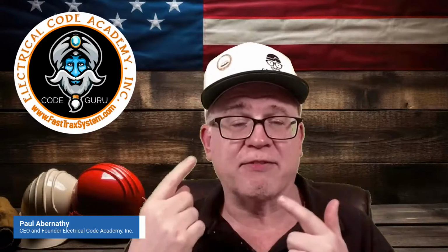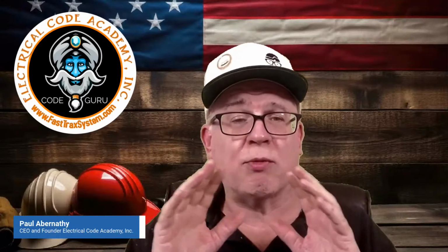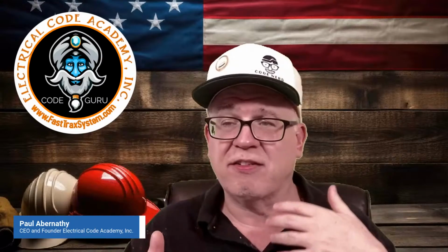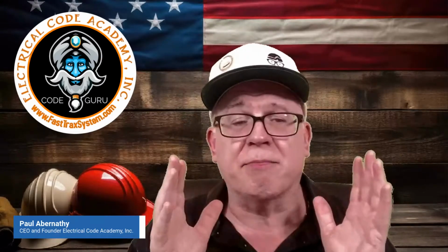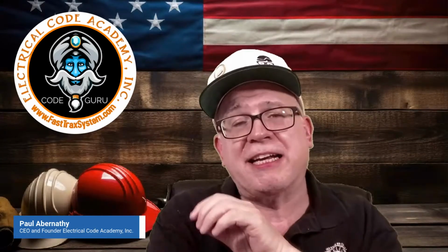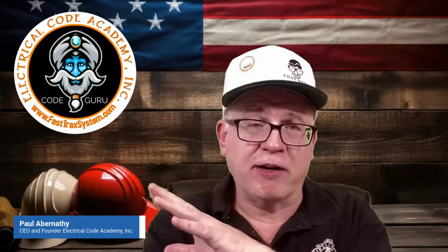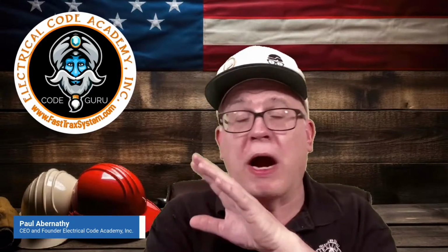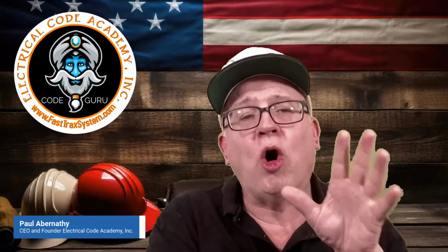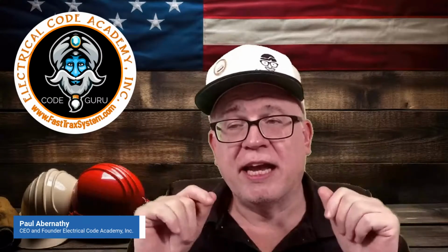It can affect electronic devices, very sensitive electronics. We don't want to risk it having any issue with anything that we may have in the house that could be sensitive and could be things like safety devices. We don't want that to have the possibility of interference, but probably more importantly, we don't want to create a condition where we're intentionally putting current onto metal parts like the enclosure, like the wiring method, if it's a metallic type of wiring method. We don't want to put current on that product in order to create what's called a touch potential issue. And that creates an issue.